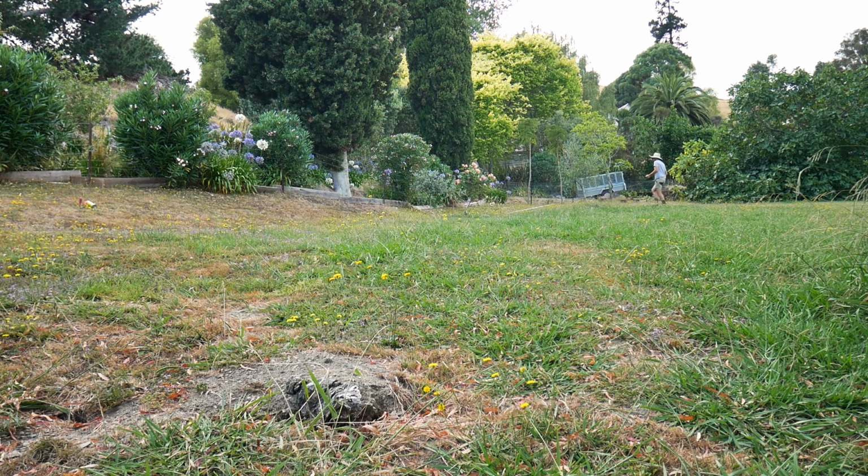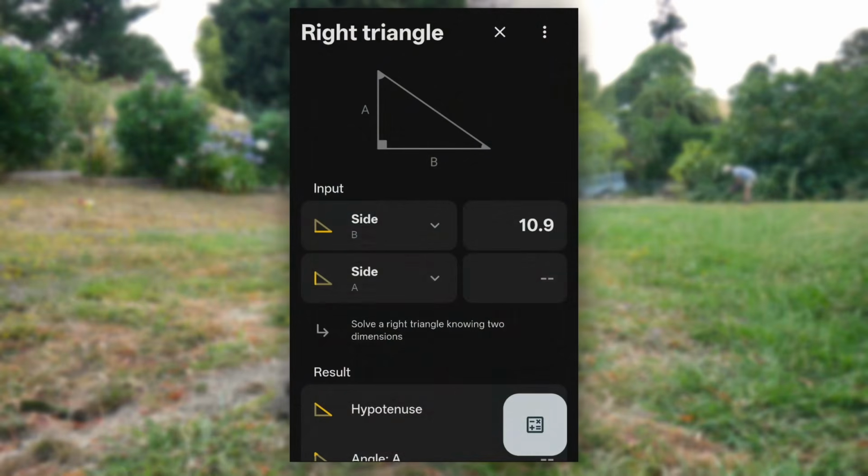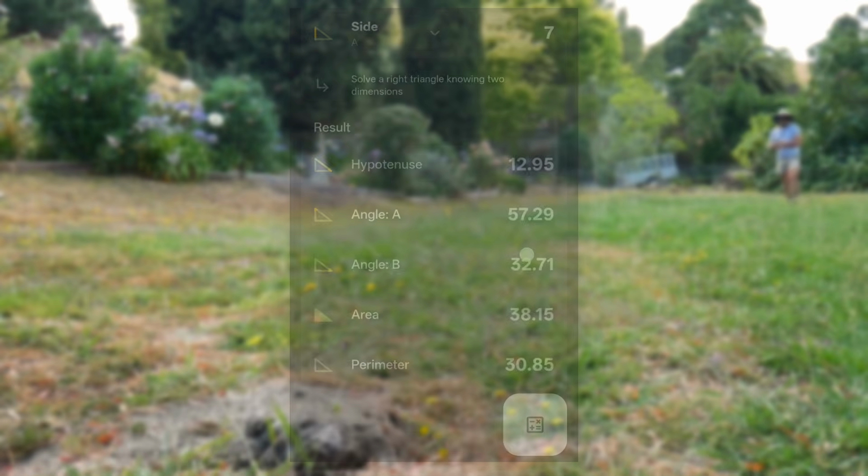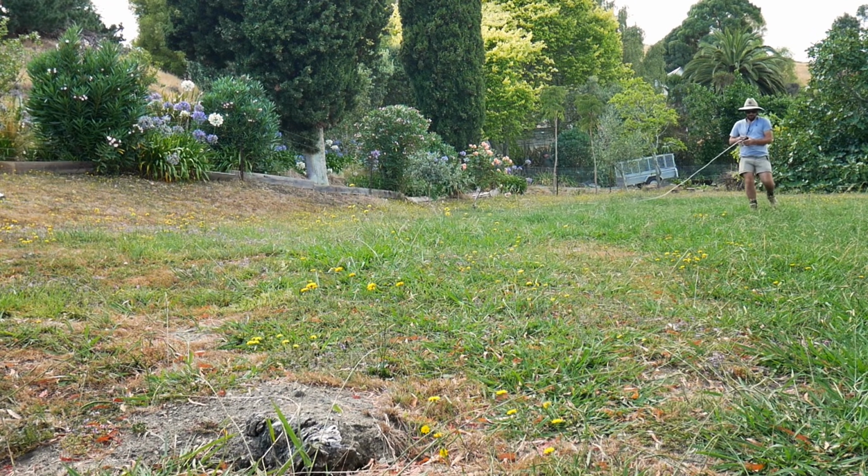This is where the memories of Year 10 maths and the early years of my career return and remind me of how far we've come. I used to use Pythagoras on calculators to work out the diagonal distance of a square or rectangle layout. Now I just use an app on my phone. I swing a tape measure from each peg along the wall length and the diagonal distance, and where these intersect is my next corner.